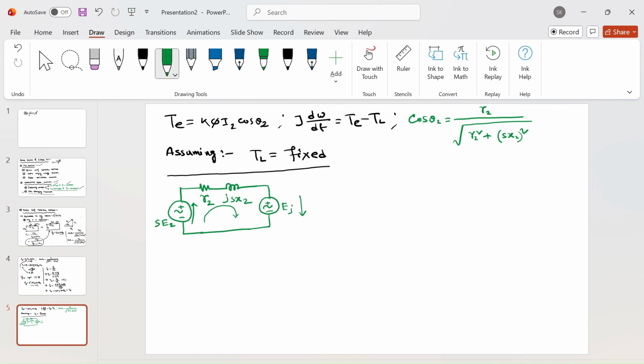But from external observation, you can see the polarities of both sources are in the same direction. Okay, these are required for the phasor analysis. We will do the phasor analysis also. So the injected voltage and S E2 are in phase opposition from the circuit point of view once you travel through the circuit.